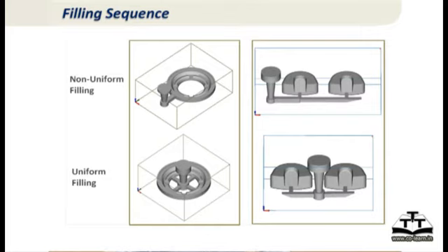In the other example here, we see that there are two cavities connected by a sprue and the runners. Now we have put a sprue at one end. As you know, the metal is going to flow to the farthest gate first, and that cavity will fill faster. The second cavity fills a little later. If you want a little more uniform filling of both cavities, I would rather have the sprue in the middle. Then, whether they are equally good or equally bad, either way I can control the properties much better if they are more uniform.